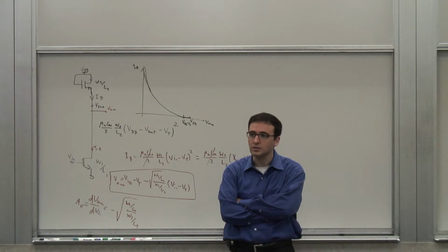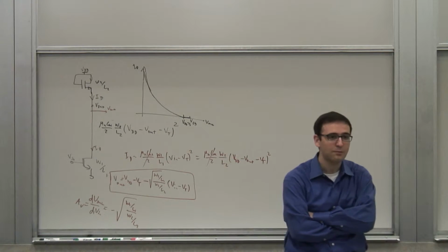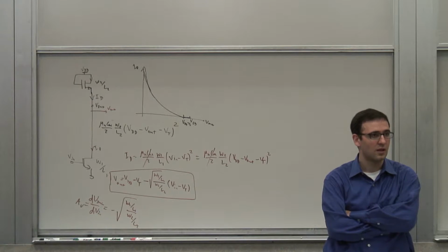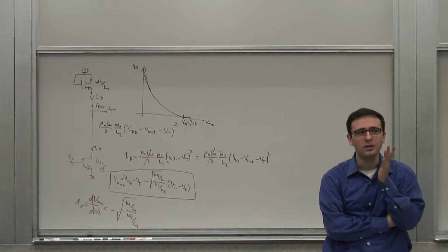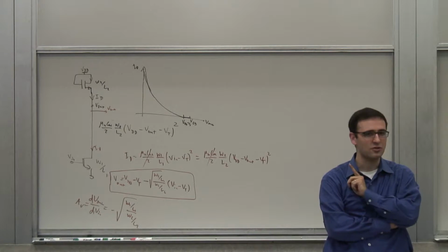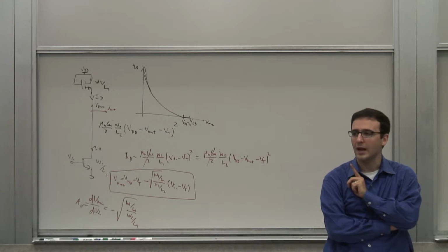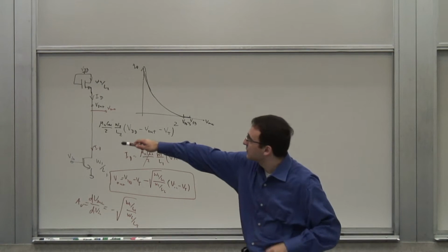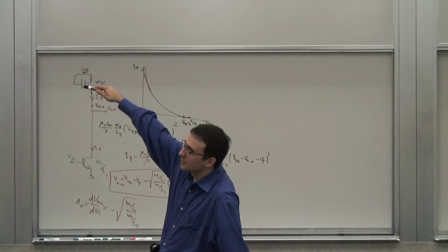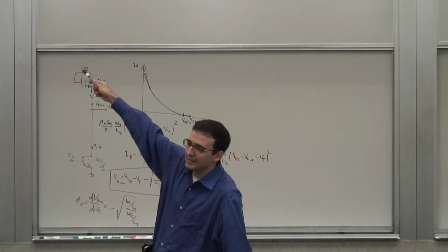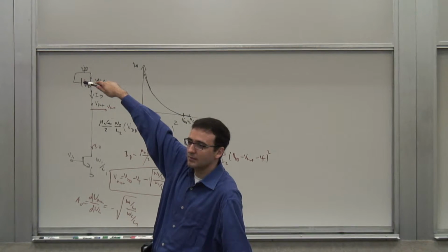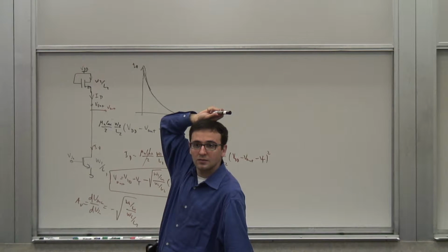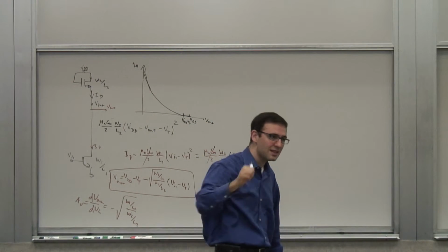That's also important. Designing a linear amplifier is important, and it's potentially a good thing. Because if you look at all the other expressions that you have for bipolar, we had an exponential dependence, right? For the basic common source stage up there, you had a quadratic dependence between V in and V out. See that black equation up there, V out versus V in? It's a quadratic dependence. This is a linear dependence.